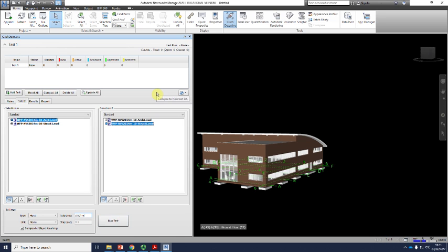There's another problem with changing units in Navisworks. Make sure you work with millimeters, or meters. Make sure the tolerance is set at the right number and the right unit. If you don't do that, you may end up with zero clashes.